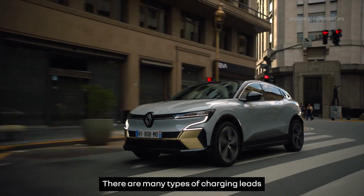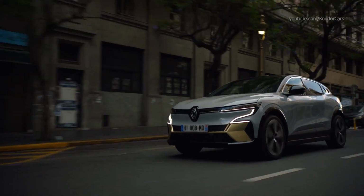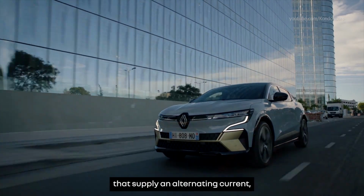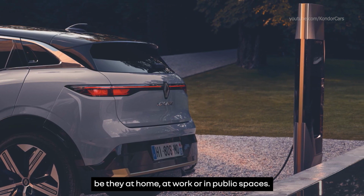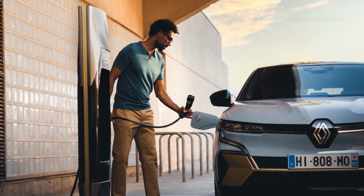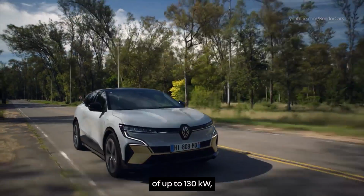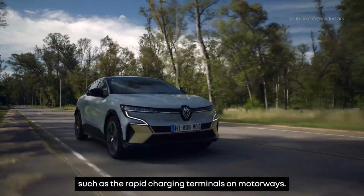There are many types of charging leads that you could use to charge your vehicle's traction battery. This means that your vehicle is compatible with all charging infrastructures that supply an alternating current, be they at home, at work, or in public spaces. Some versions are also compatible with charging infrastructures that provide a direct current of up to 130 kilowatts, such as the rapid charging terminals on motorways.